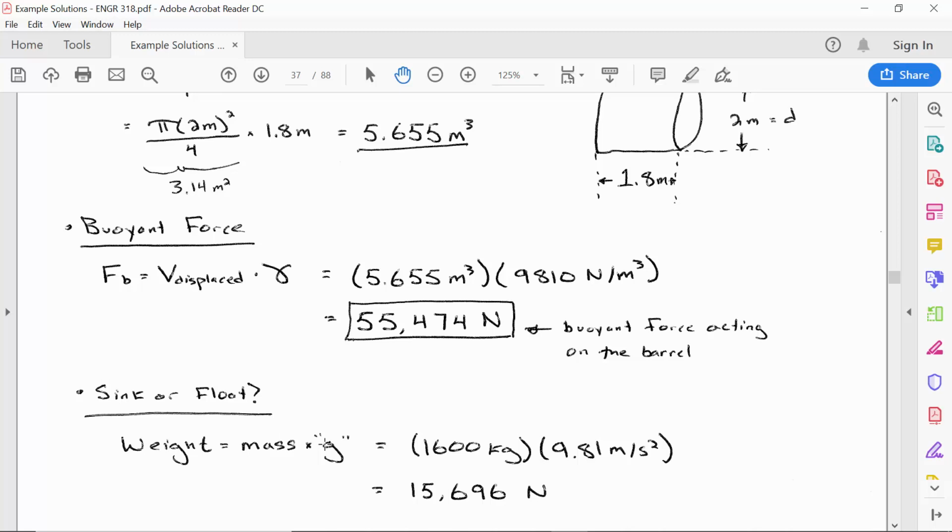And it is. I actually have a homework problem that you didn't get this semester, but it's a really interesting one about what if you have a waterproof scale, and you're measuring something like a concrete cylinder, and then you move the cylinder and the scale underwater. Then all of a sudden the scale is saying something different. And so with the before reading and the after reading, could you calculate the density of the object? It's a tricky question when you look at it. From the standpoint of that scale, it will give you a different measurement underneath the water, but it's not because the mass changed, it's because the buoyant force is taking effect when you submerge it. So anyway, the answer is yes, g is the same whether or not the object is submerged or in the air, the gravitational constant stays the same.